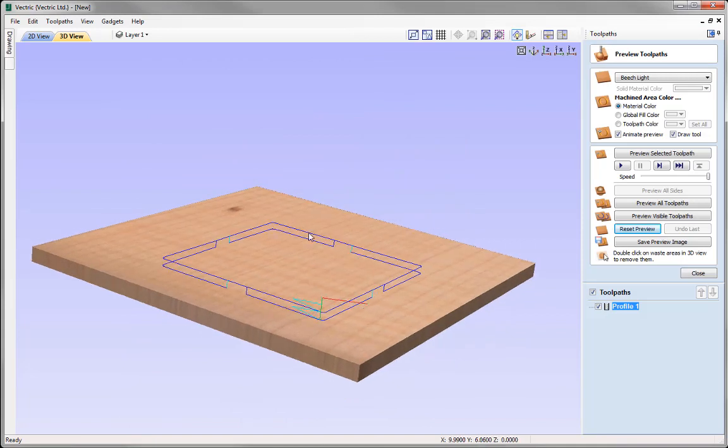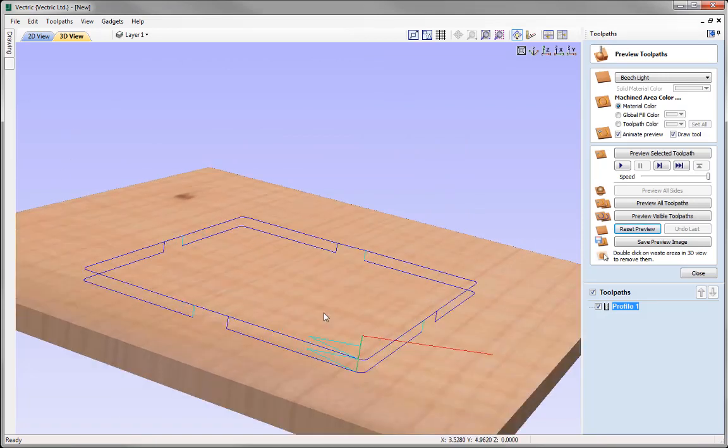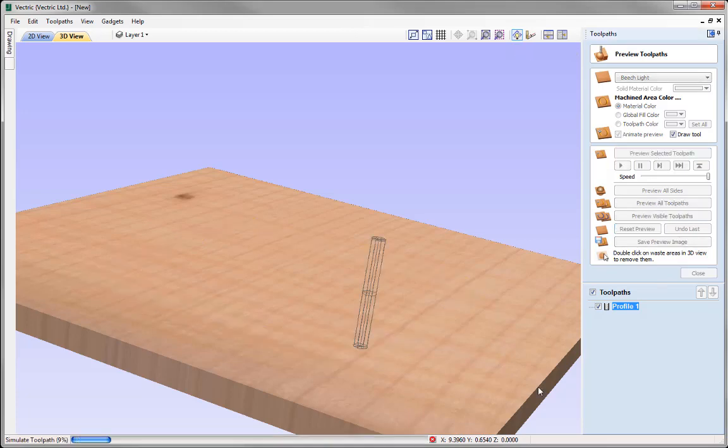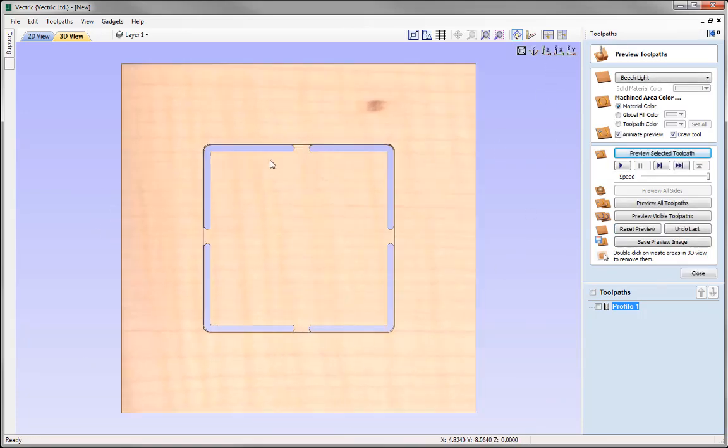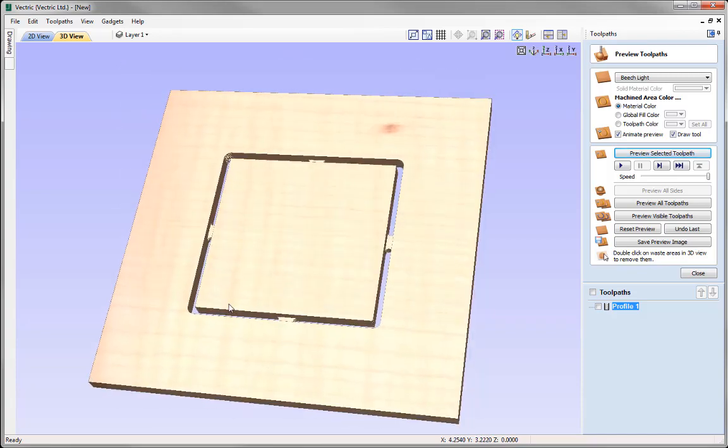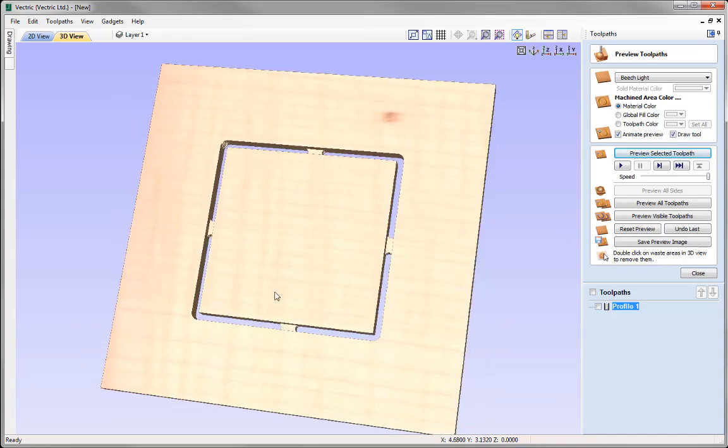And so then if we just tilt the view here, we can see how this toolpath is going to look. So it's going to ramp in, go around, cut the first pass, ramp into the second pass, come over. As it gets to a tab, it's going to retract up by 1/4 of an inch, as that's the thickness we specified for that tab. It's going to come across and it's going to plunge back down to the pass depth of 1/4 of an inch and go round until it meets the next tab. So if we go ahead and preview that toolpath, we'll just put that in the Z view, you can see those tabs in position there, and that's going to hold our part in place.